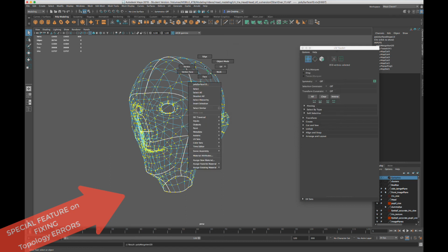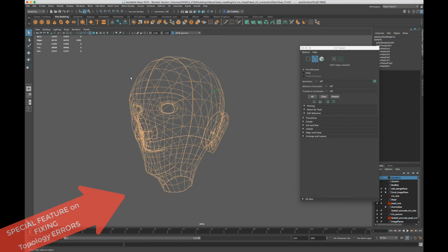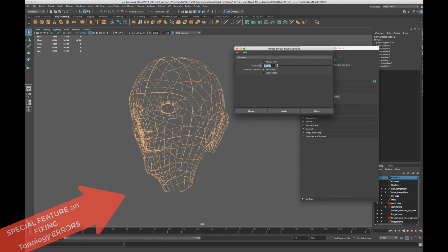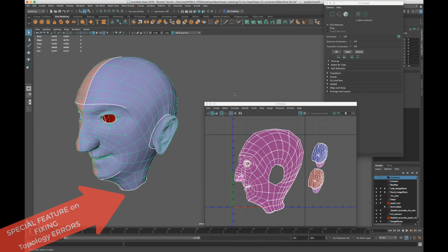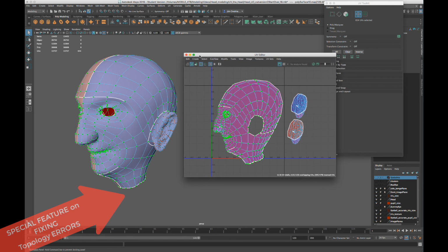Now we're going to do the same thing but with edges. So we select on the components, this time edge, and then we're going to select the whole mesh that's in question, not missing anything. Then quite the same thing, we go to the merge option box, but this time you could put 0.01 would be a better setting for it, and then merge. Okay, that could have taken care of that needle in the haystack, whether it dealt with CVs or edges. And if you merged all CVs and edges in the proper uniformity, faces fall directly by the wayside. So they too must be correct if the others are.